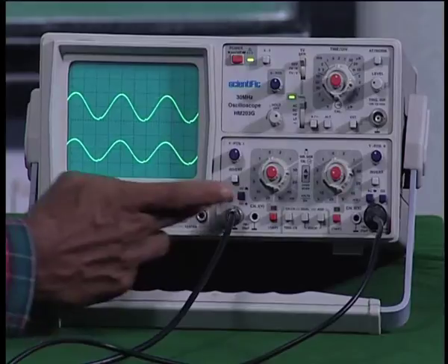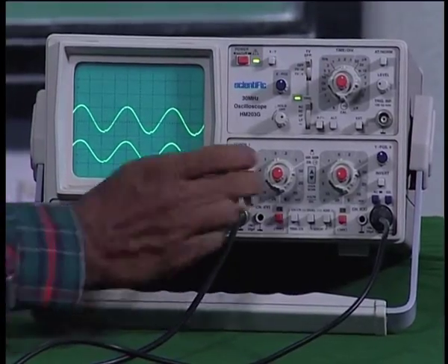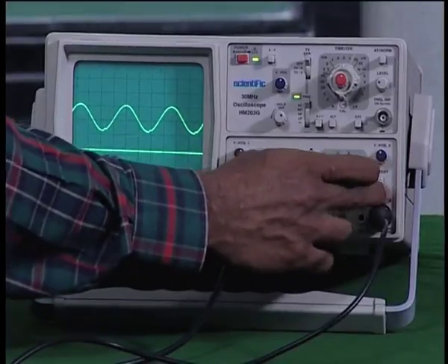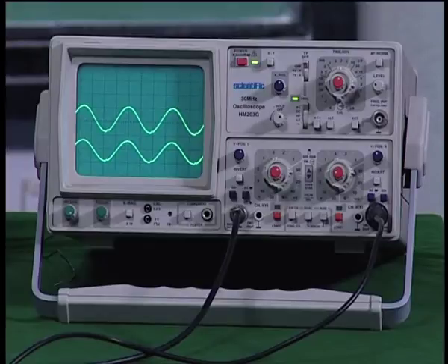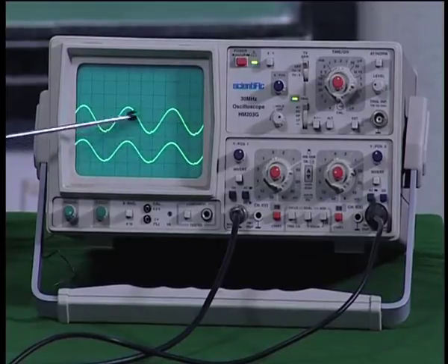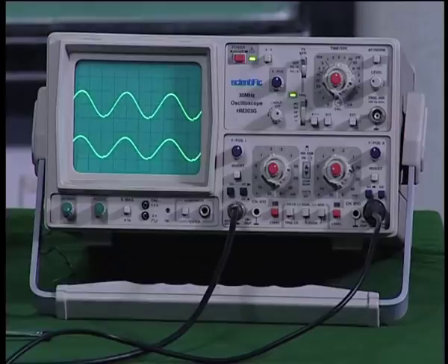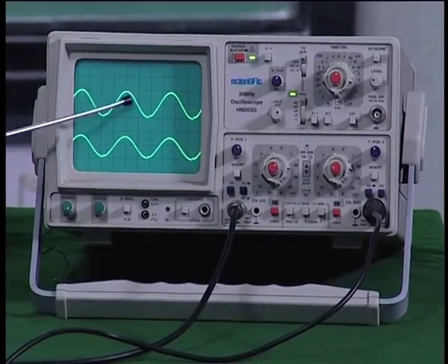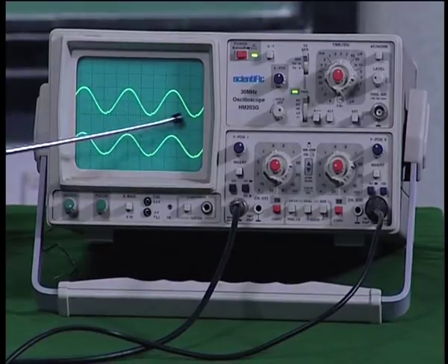So, for example, I have a knob here, which when I press, you can see this is now AC mode, this is DC mode, AC mode. So, you can see in the bottom sine wave, the AC is with reference to the ground, which is here. For the top one, you would find when I make it into DC, you find still the sine wave is there, and it is moved up to this line, the central line.